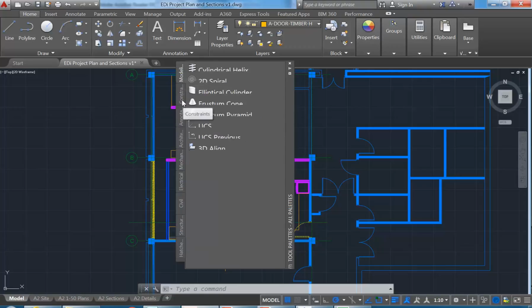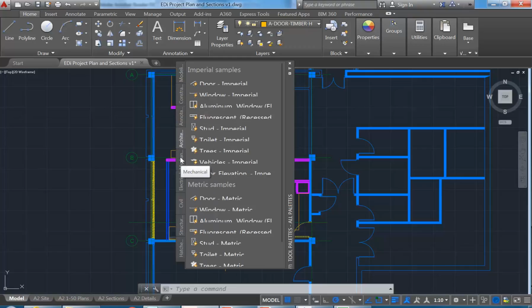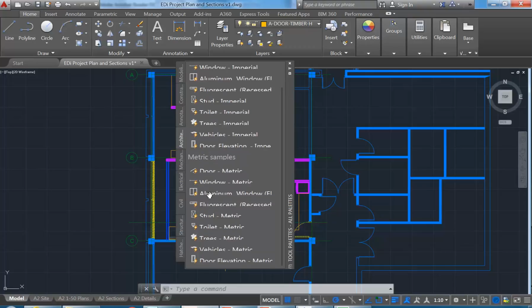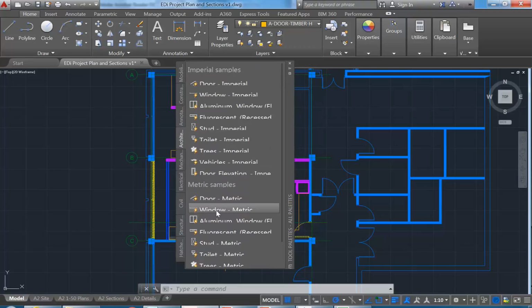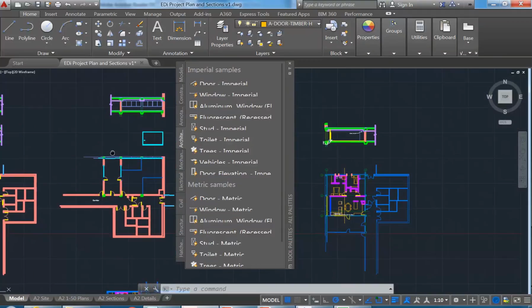but they're set up by the guys at Autodesk, and they often use maybe some of the new features that aren't always the most workable. So I've been showing you the way that AutoCAD's been used traditionally, which is using things that aren't done with these new features like dynamic blocks. And have any of you tried to use dynamic blocks up until now? They're good in some cases, but I think sometimes they're more trouble than they're worth. And so you'll see here there are doors and windows in this palette, which is architectural. But again, they use dynamic blocks, which can be problematic.